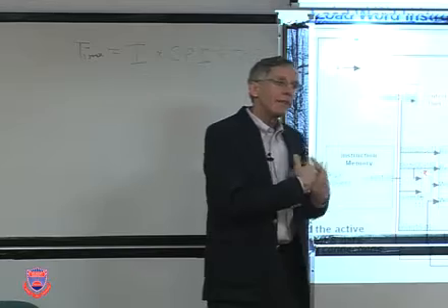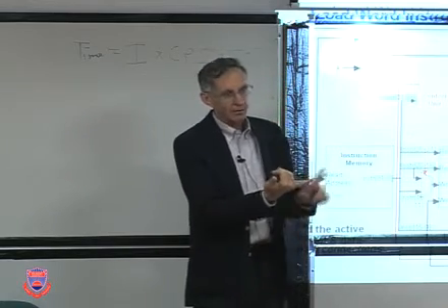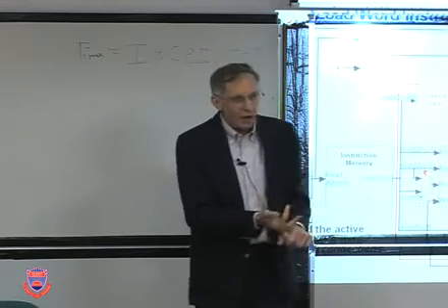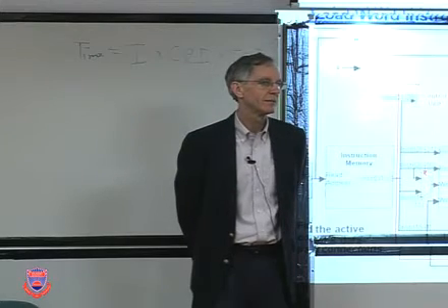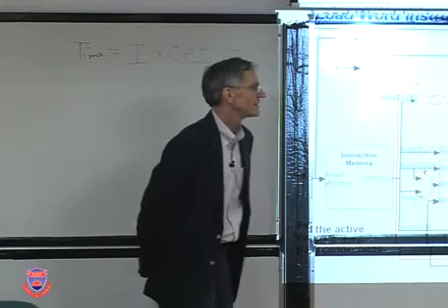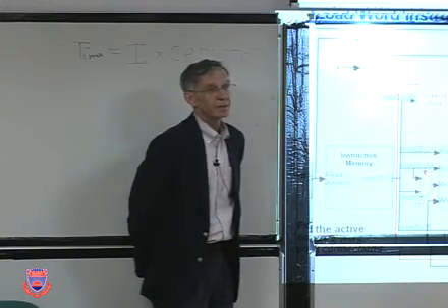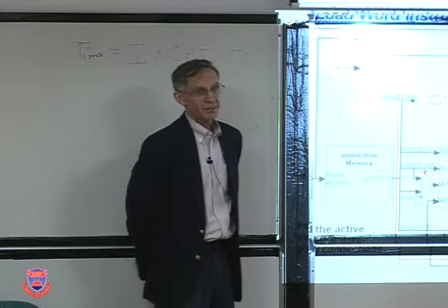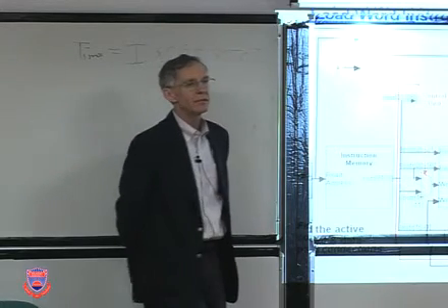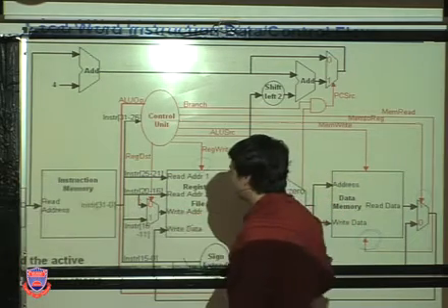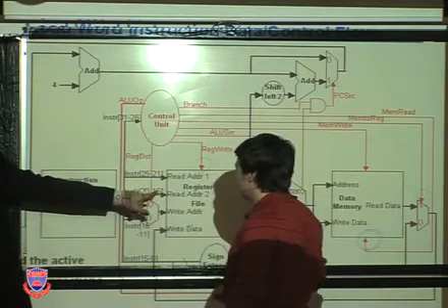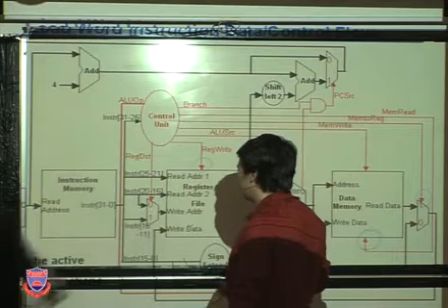Great. Then that means that you use the op to decide that it's a load. You used RS and you used the immediate. What's left over in the I format? RT. So what is RT then? RT is the destination address that we're going to put that value from memory into the register file. So which one of these two is RT? Is it bits 20, 19, 18, 17, and 16, or is it bits 15, 14, 13, 12, and 11?